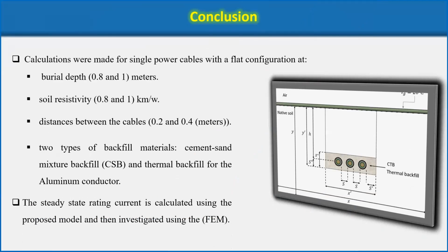Conclusions were made for single power cables with the flat configuration at burial depths of 0.8 and 1 meter, soil resistivity 0.8 and 1 Kelvin meter per watt, and distance between the cables 0.2 and 0.4 meters. Two types of backfill material: cement-sand mixture backfill and thermal backfill, for an aluminum conductor. The steady state rating is calculated using the proposed model and then investigated using the finite element method.